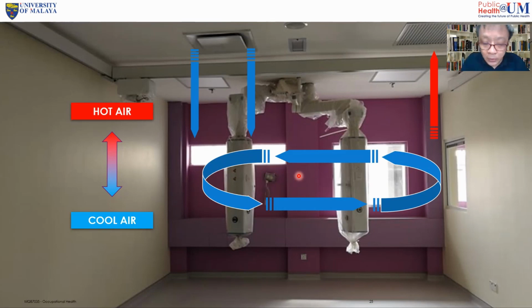In a place like an ICU or a hospital environment, the air exchange is up to 12 times or 20 times an hour. So 20 times the air change per hour. Why don't we do it in an office, to increase the air exchange from 4 times to maybe 12 times or 8 times or 20 times an hour? Why don't we do it? Anyone?